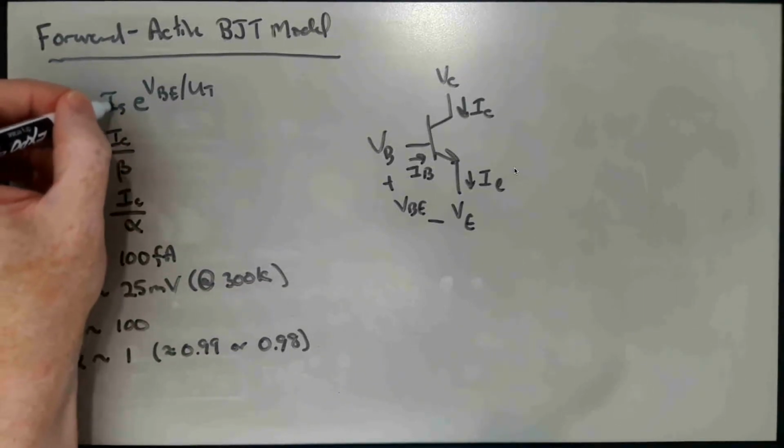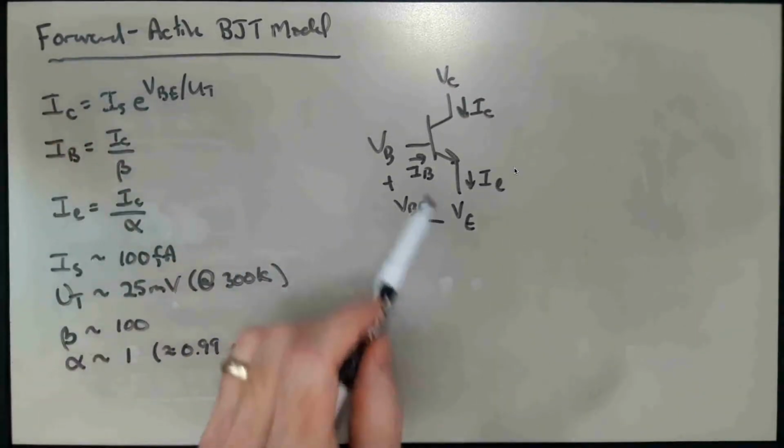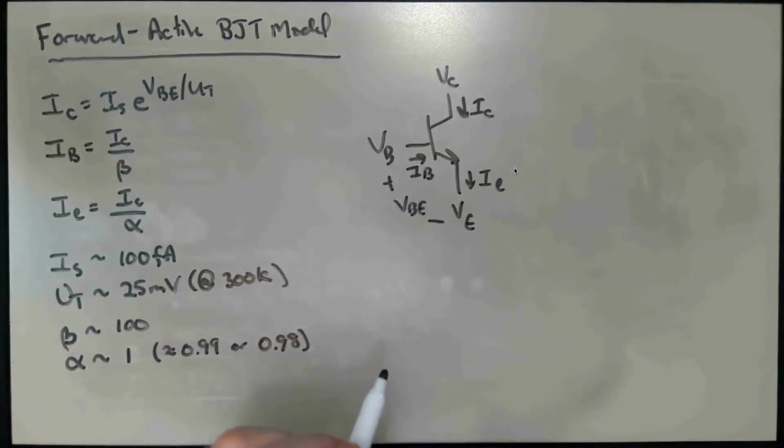Okay, so from the standpoint of the collector, it's like a current source. And a transistor, biased in the active mode, is a reasonable sort of first-order implementation of a current source. We can make better current sources if we throw an op-amp at it or throw more transistors at it. But this is actually a pretty respectable first-order implementation of a current source.